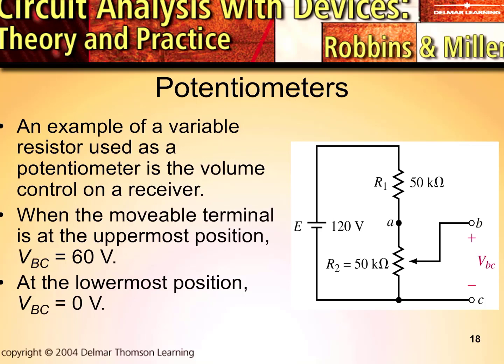Okay, so if we look here, we can look at this as a voltage divider, but a variable voltage divider, and it's just looking at that potentiometer example like we used in the E-lab, except it's wired differently in this case. All 3 terminals are connected. So that means you have a terminal connection on the top now, and on the bottom, and a terminal on the what's called the wiper that can be adjusted up and down.